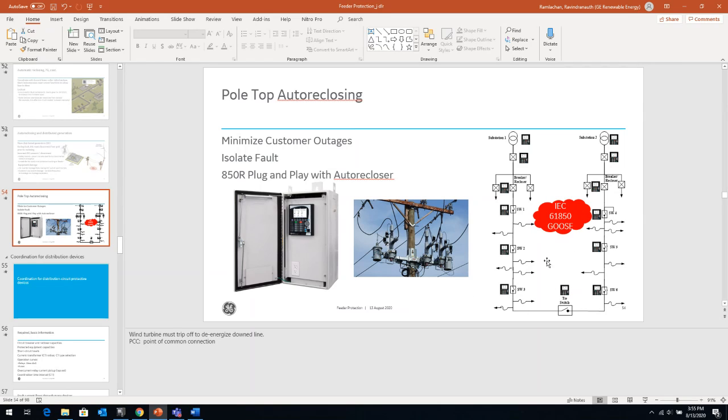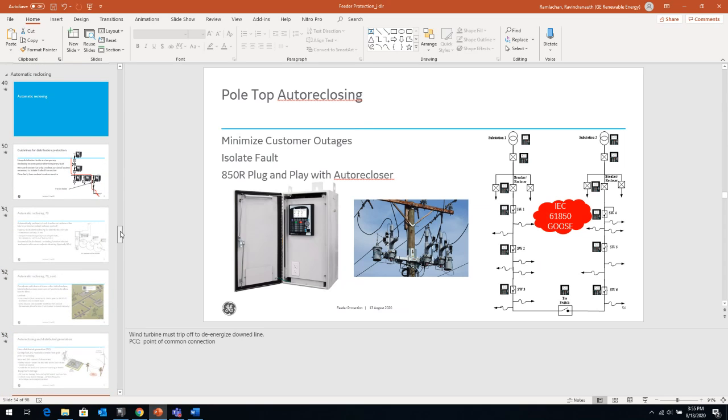So we can use IEC 61850 to do some sort of recloser automatic coordination, auto reclose schemes. Say we have a fault out in the feeder, we can bring all that information back, determine where the fault is, and then switch around that fault automatically. So there's a lot of intelligence we can do with that. The other one was the zone interlocking I talked about.